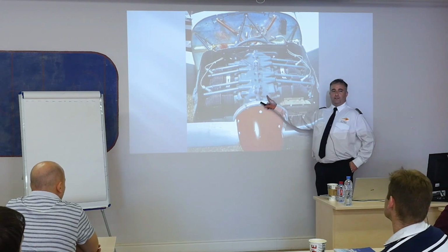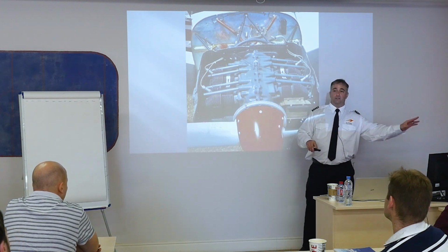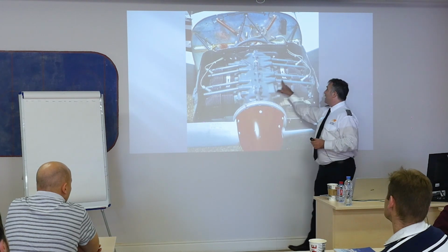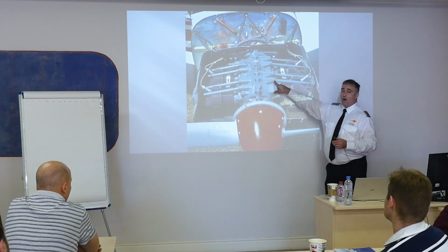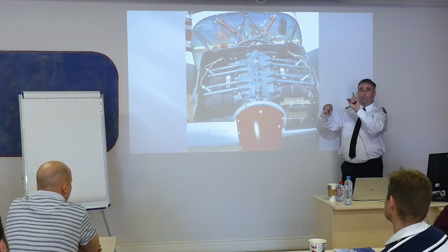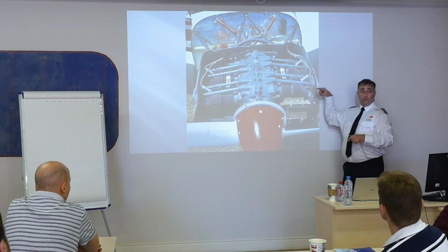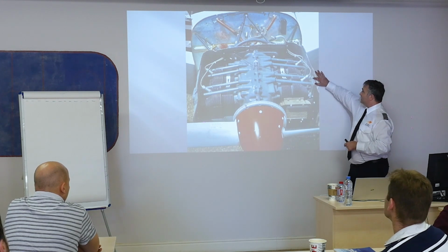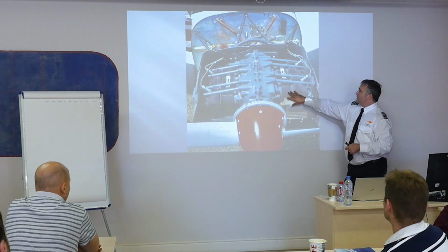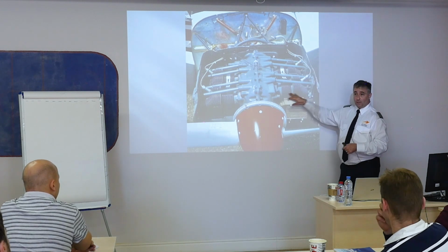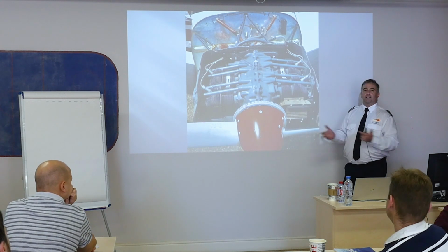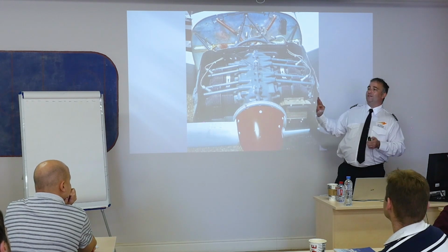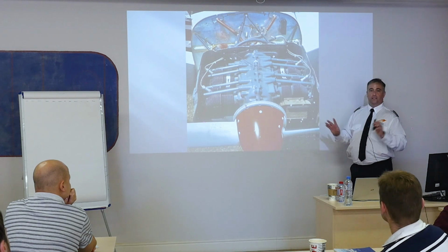Now, inside the crankcase, there's a thing called a camshaft. Forget I ever said that because they will never mention that in any of the books. But there's a camshaft that goes through here, has lobes on it, and these lobes push a rod out to the valves. And the valves open and close and either allow air to come in through the induction system or to escape through the exhaust. So I got cylinder heads out here. These are the valves. These are the cylinders. And inside the cylinders are pistons that move back and forth. This is the basic components of the internal combustion engine. Don't go even anywhere close to beyond that because that's all you need to know.